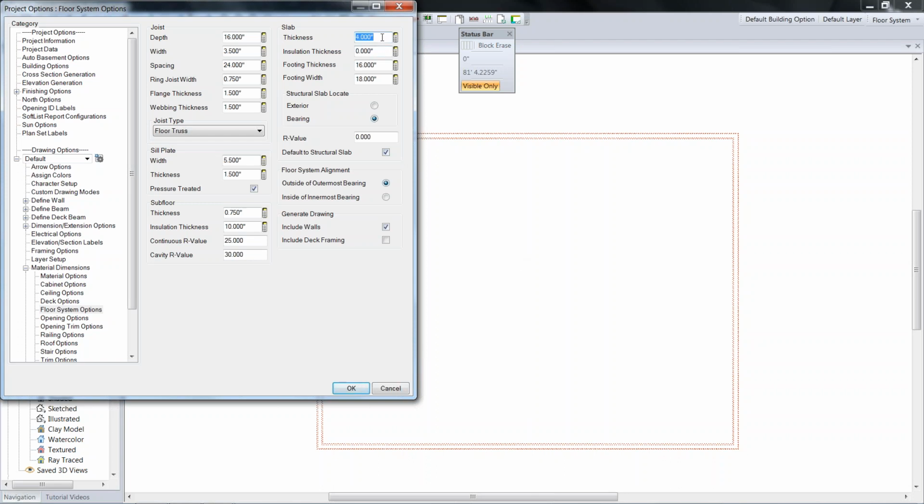And it's telling me it's going to be 4 inches thick. It's telling me there's no rigid insulation underneath the concrete of the main part of the slab, and there shouldn't be. It's telling me that the footing thickness, that would be the depth, is 16 inches deep, and the width at the bottom is 18 inches. By the way, very important, Florida users, this footing thickness is measured from the bottom of the slab to the bottom of the footing. We have a tendency to shortcut this. When we look at a monolithic slab, we'll say it's got a 16-inch footing, but we're measuring it from the top of the slab. No, that's not how SoftPlan does it. Footings are footings, slabs are slabs. So this is going to be 16 inches. And if you're building in Florida, then you might say, well, that's got a 20-inch footing system. Fair enough. So I'm going to say okay to that.